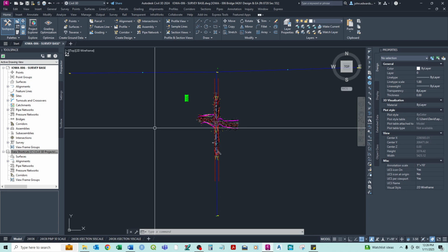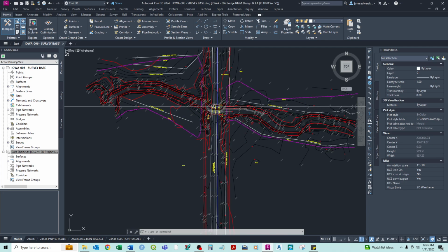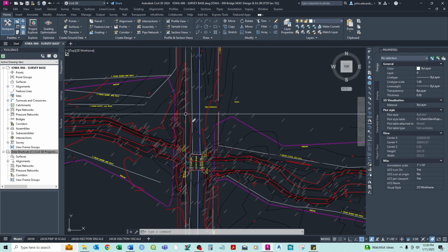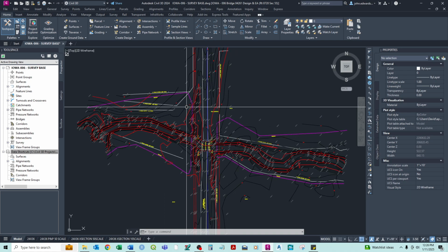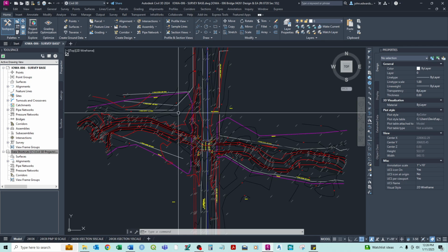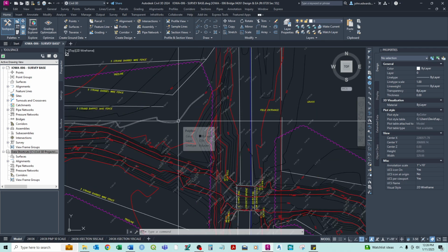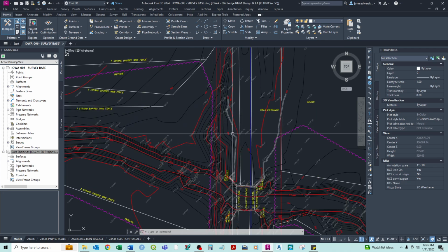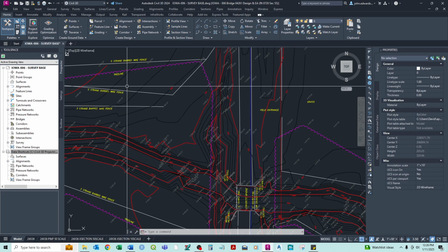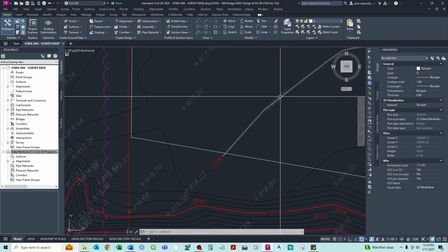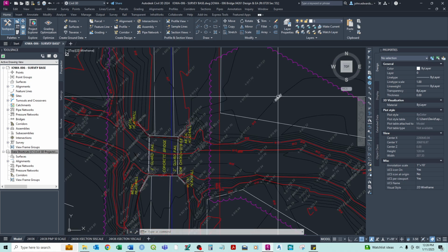So now one thing, we can go in and maybe clean this drawing up a little bit. When we bring in this XREF, we probably don't need all the contours as polylines and the labels, because we can do that specifically with the surface. We probably don't need all these individual elevation points as well.